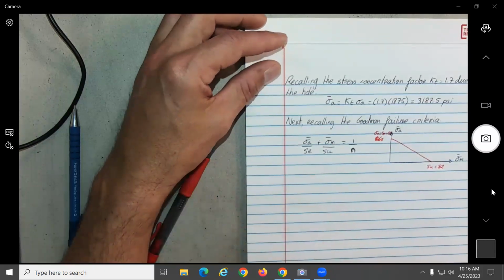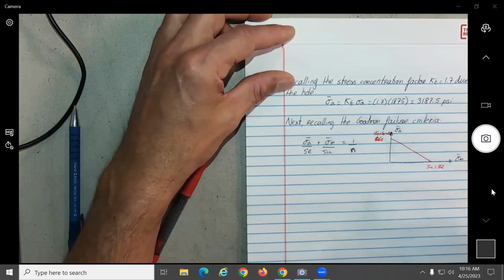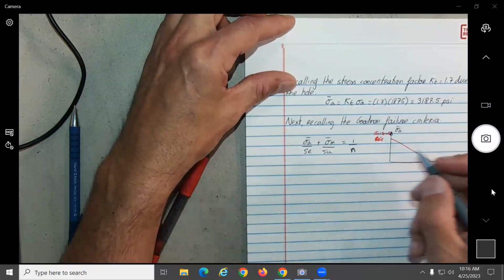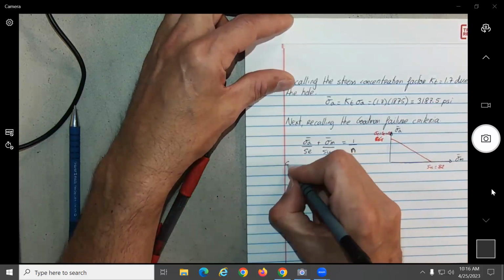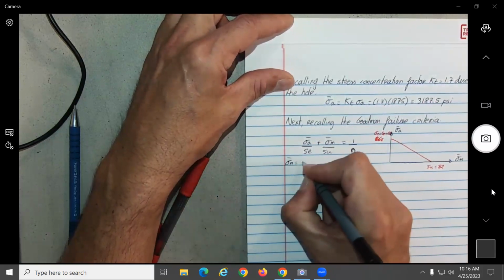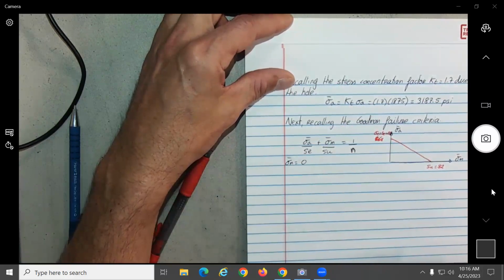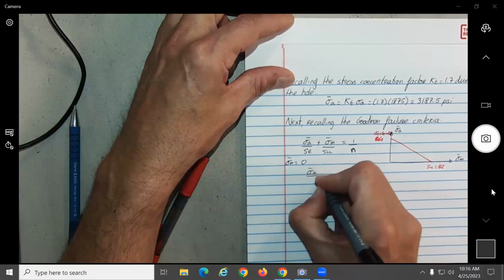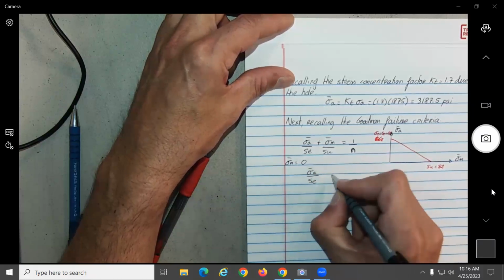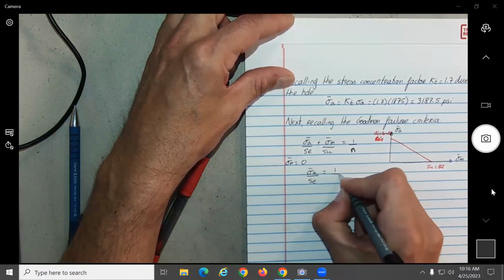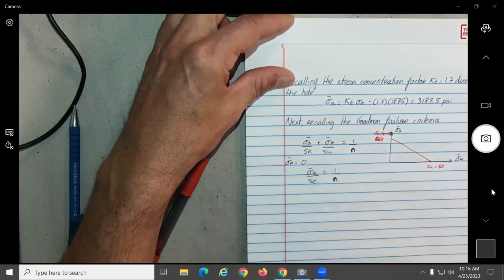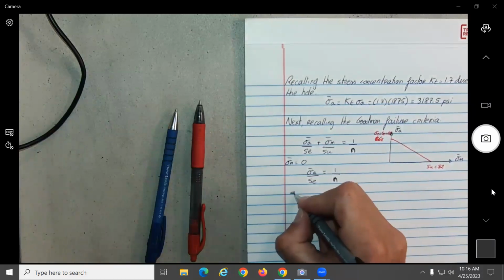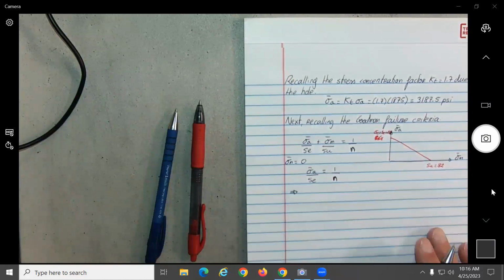So that figure again, leave some space on top of the figure, okay? So in this equation for us, what is sigma m? 0, no? Okay. So really for us, this becomes what? Sigma bar A over S endurance needs to be equal to 1 over N. So first, without even looking, is it going to be safe or not safe? What do you think?